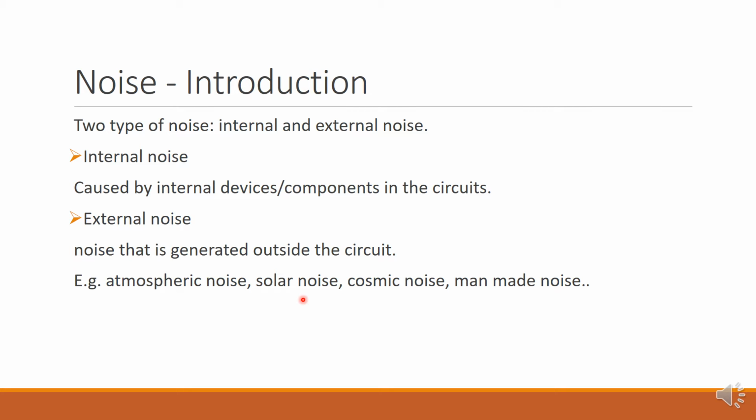For solar noise is a normal condition. There is a constant noise radiation from the sun. It is simply because a large body at a very high frequency radiates over a broad frequency spectrum. This also will, as a result, give you a certain amount of noise towards your system.